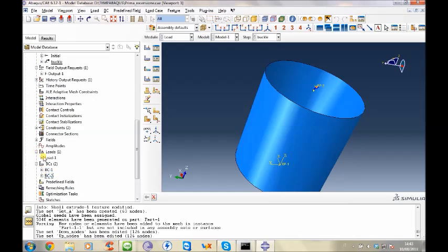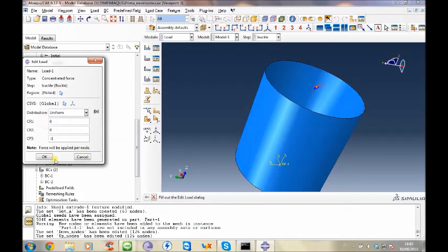And then, always applying the load to reference point 2, we set 0 for x, y, and zeta, the third component of this vector. I select minus because the direction is minus, and 1 because the eigenvalue will be proportional to this value.